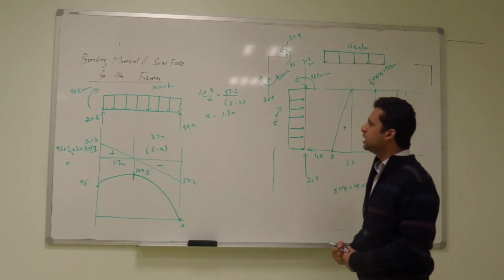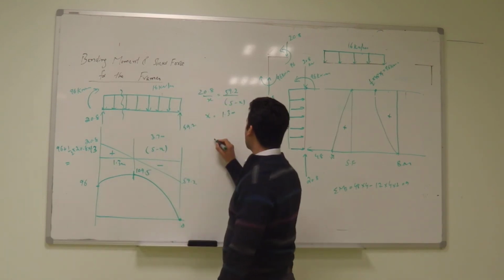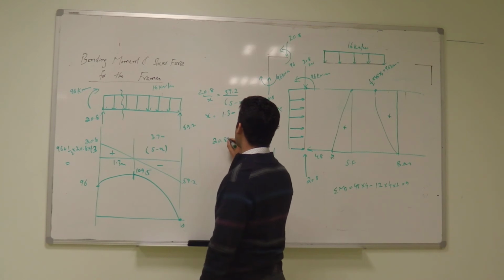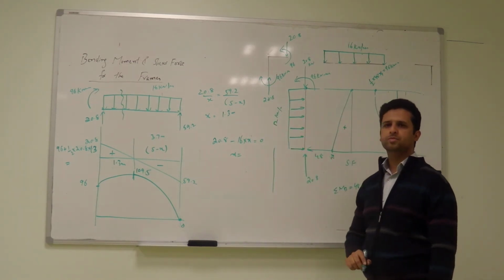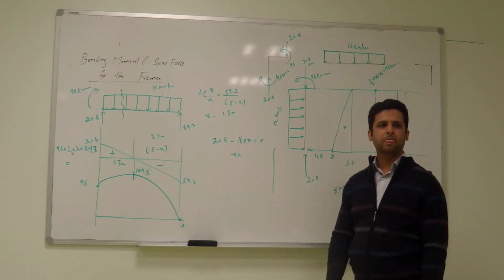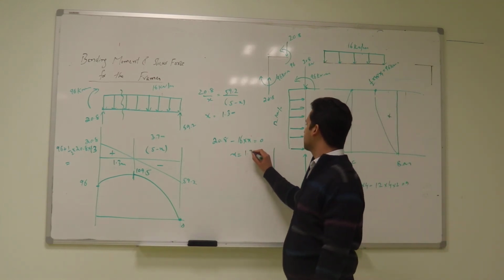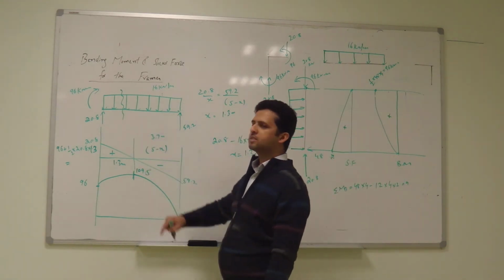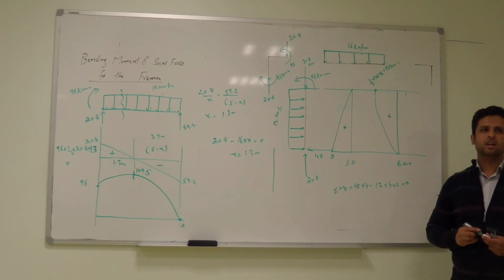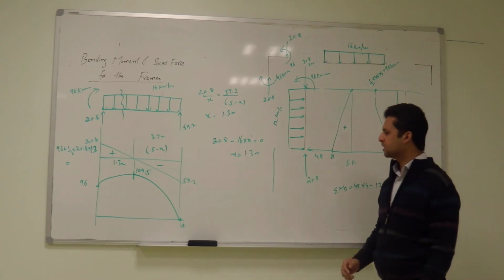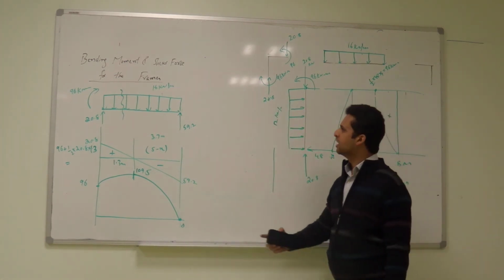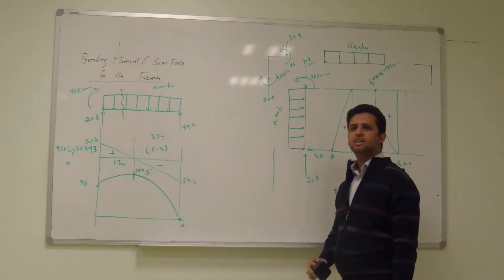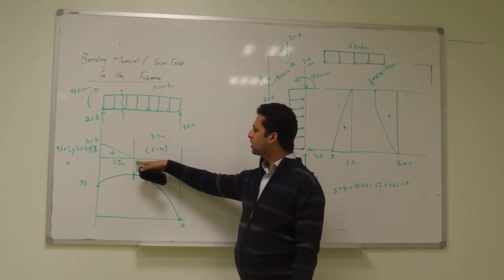You can also do it by writing an equation for the shear force. Like 0 equals, for example, 20.8 minus 16 into x at that point. Check how much is x. Okay, 1.3. This is the other way. Write the equation for shear force here. Do you understand? Yes. It is shear force, 16 into x, not the moment. 1.3. Because where the shear force V is 0, we have a point. 16x downwards.